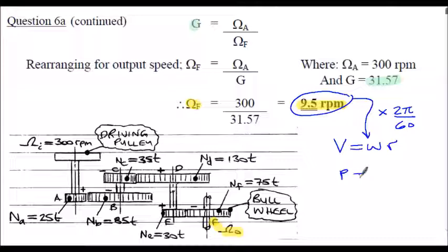We know the pitch, it was 25 millimeters, I think, so I'll put that in meters. So we're given the pitch. Now, how can I relate pitch to diameter and number of teeth? That's the way I'll be thinking now. I know the number of teeth on the output gear is given in the question. I've got these 75 teeth. I've got the pitch of the gear. Is there any way I can find the diameter from the relationships we've looked at before? These little formula sheets are quite useful. You can browse through your formulas and see what's relevant in this case. We know the pitch, we know the number of teeth, we need to find the diameter.